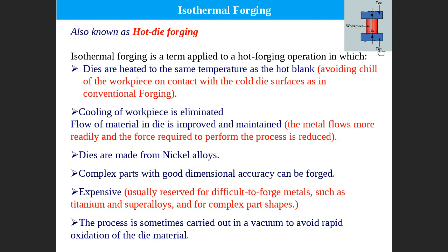You get non-homogeneous deformation, which leads to high internal residual thermal stress. This leads to some defects, especially in materials like titanium, materials with low thermal conductivity. Because it cools down easily at the edges, but because of low thermal conductivity the middle is still very hot, you get a very high temperature gradient between the edges and the middle, non-homogeneous deformation, and many defects.